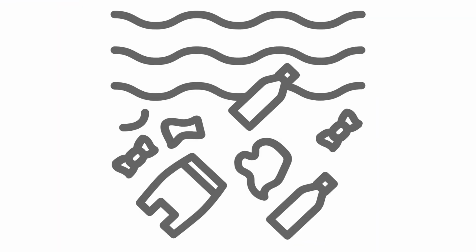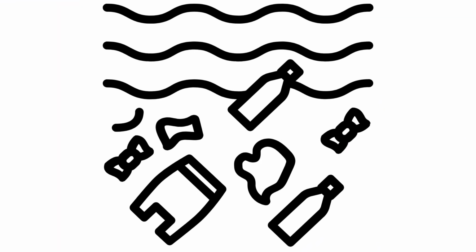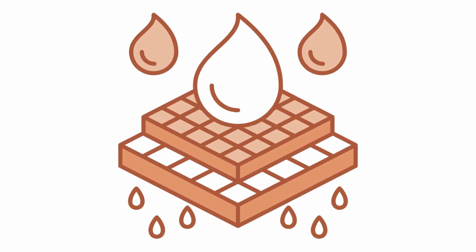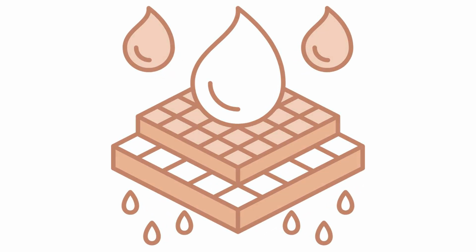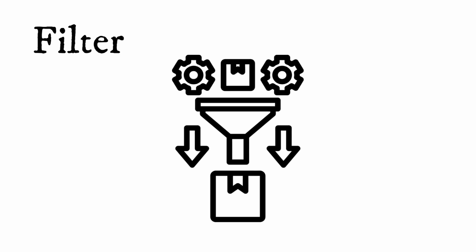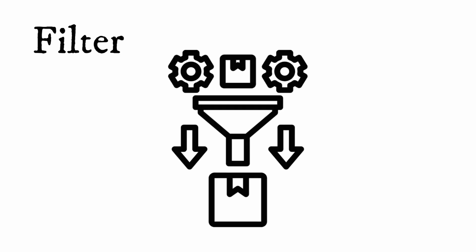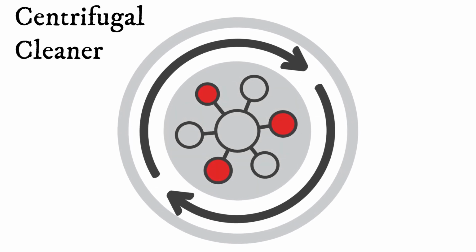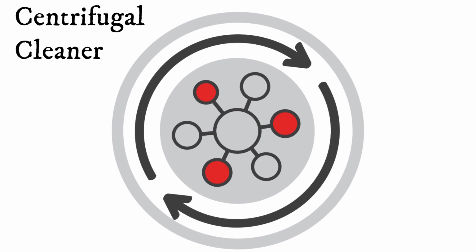Then we have pulp refining and cleaning, and the pulp is cleaned to remove impurities, such as dirt, ink, and small particles, using screens to filter out large debris, and centrifugal cleaners to separate heavier contaminants. Refiners beat and condition the pulp to improve its strength and bonding properties.